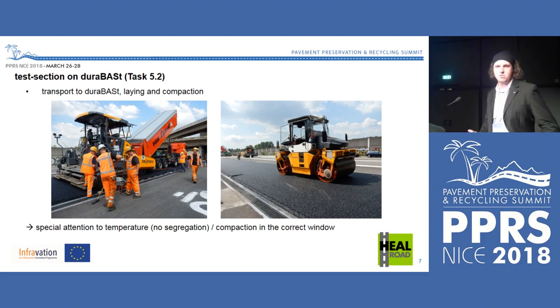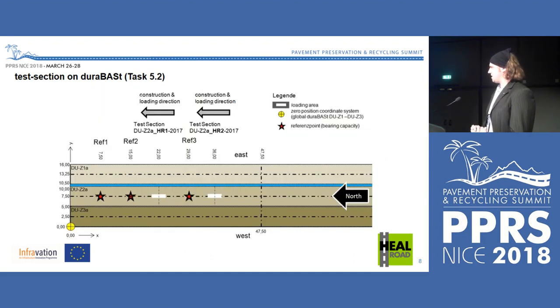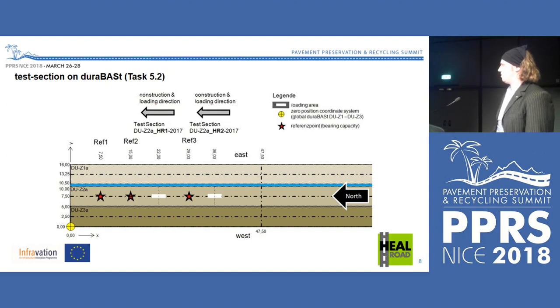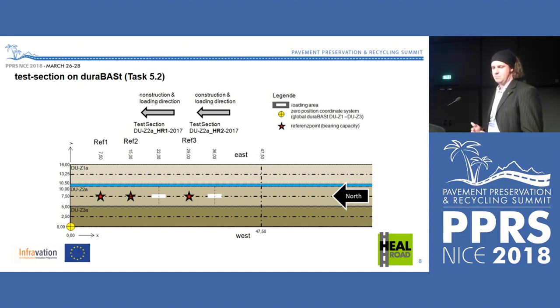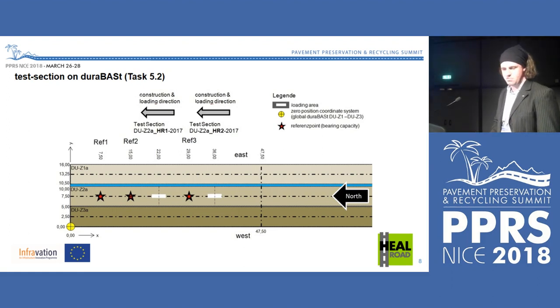So we don't have to adjust anything on the paver or on the rollers. You build up porous asphalt conventionally, you don't have to think about anything else. After the construction, we had a demonstrator which was approximately 50 meters long, and we placed 2 loading sections. One was our so-called reference track, HR1, and this presentation is more on HR2, where we implemented the healing actions too.